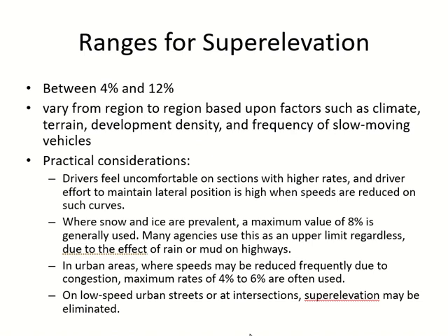Superelevation should range from 4% to 12%. I mentioned this in the last lecture as well. But this is the normal range. It can be less than 4% as well. Can it be 0?